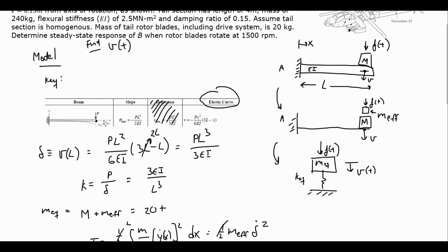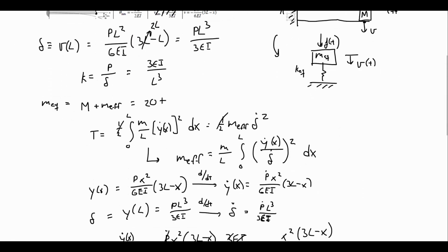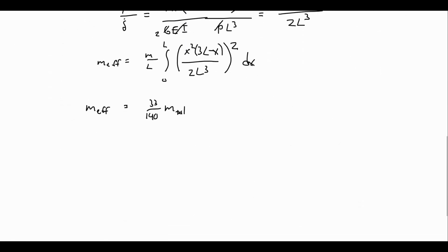And then we are also going to need to know the forcing function that is acting. So we have this eccentric mass that's rotating. So our f of t, eccentric mass is rotating. We're going to use m. Here, this little m is the weight of that eccentric mass times its eccentricity times its angular velocity squared times cosine omega t.